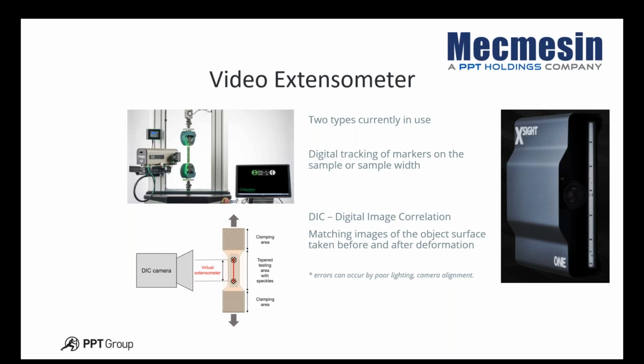And to be fair, these can get some very good accurate results, and they're very multifunctional. And there are lots of them available on the market. They can either be used as a standalone system, or they can be integrated with equipment for doing the strain measurements with non-contacting. Particularly useful for samples that can get damaged easily by a contacting extensometer.